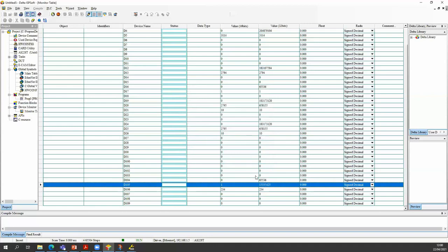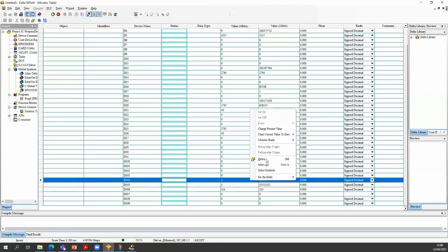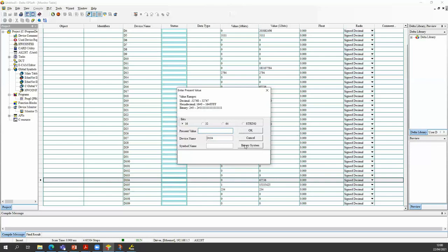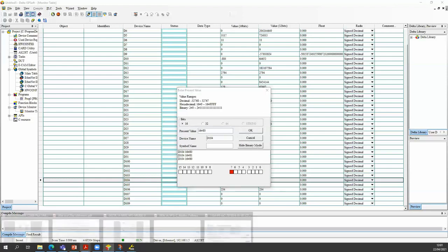Okay. So I'll give a run command firstly. So servo on, and I can see the frequency is set to 0. And for positioning mode, if I enable this, this will be the command to move to a new position. But if I enable this, then nothing happens because I've not given it any position command.